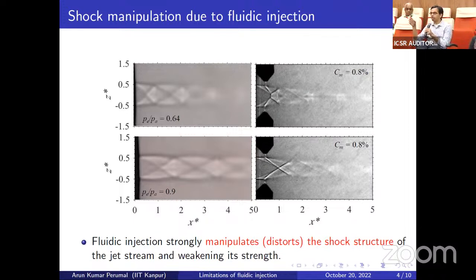Yeah. Right. Okay, good. The second question I had was on your scaling, that you had your CM times velocity magnitude. Your point was that if you want to create a greater effect, you just shrink the diameter. The issue with doing that is you're essentially creating perturbations at smaller and smaller circumferential area, and at the limit of 0, you're essentially not creating anything.